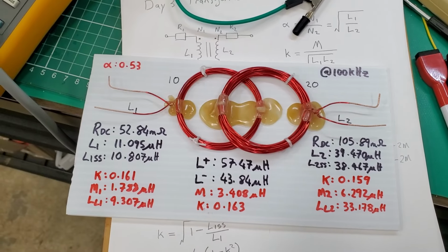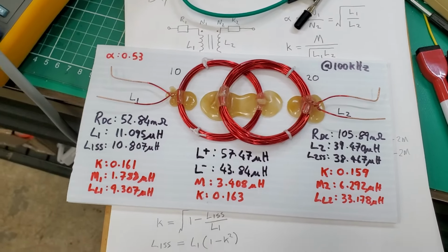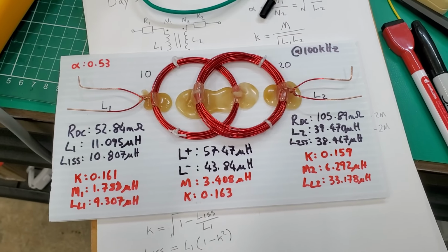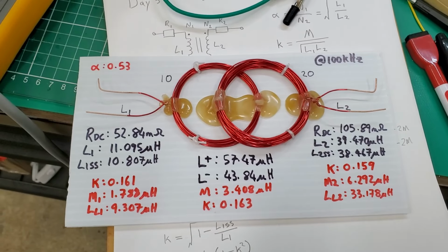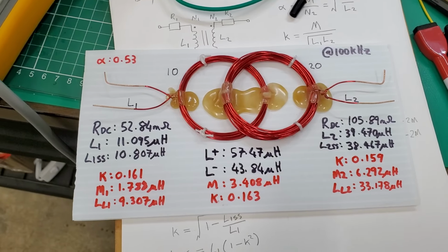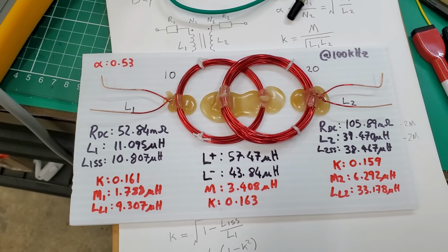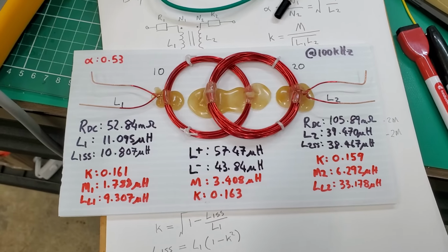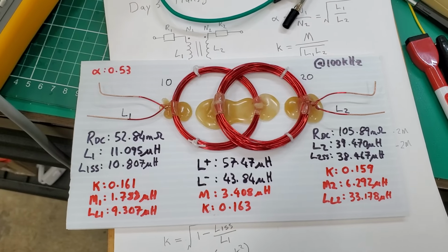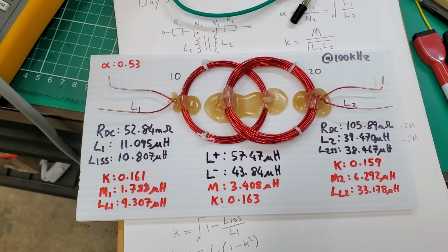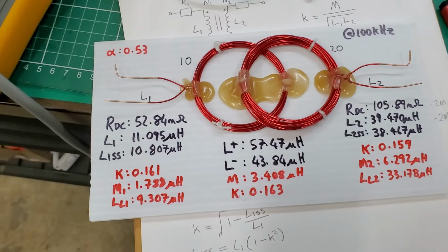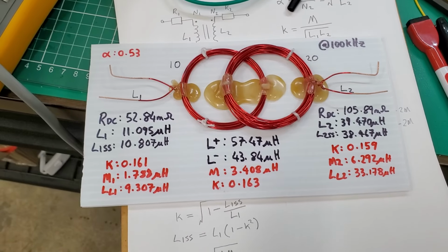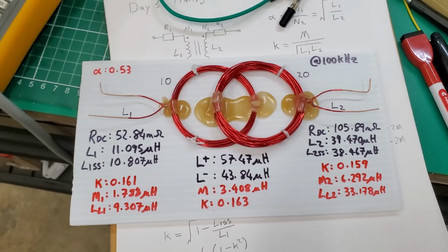But one more thing you need to be careful about, if you are measuring this at higher frequencies, is that your transformer hasn't had some kind of resonance happening. The distributed capacitance of the windings, or any kind of lump capacitance across the windings, can mean that you're no longer dealing with an inductor anymore. But in general, if you measure the transformer near the frequencies that you're going to actually use it at, you'll get the best results, right?